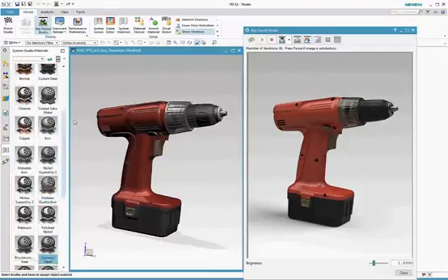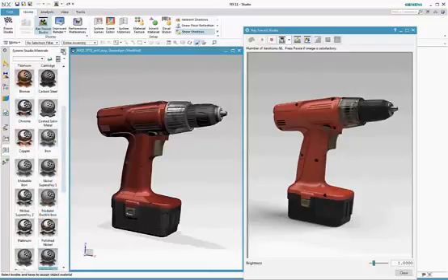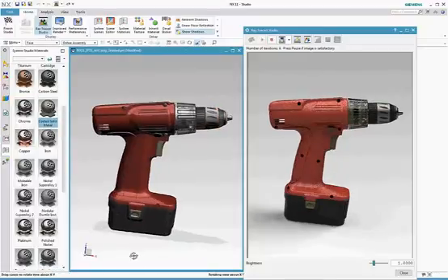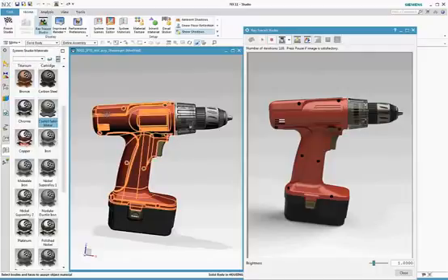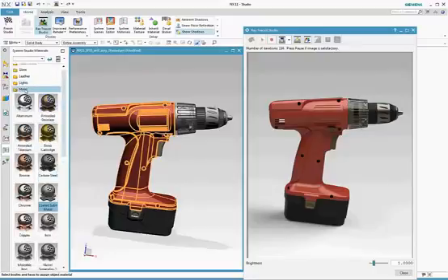Materials can be applied to bodies. To apply a material to a face, change the selection filter to face, select the face, select the material to apply it. One advantage of using the Studio task is that it provides you with operations specific to rendering setup. One example of this is Select All Objects with this material, available on the object pop-up.